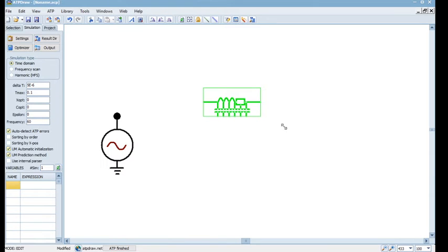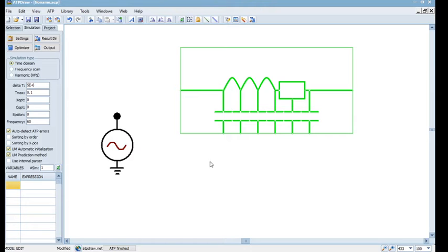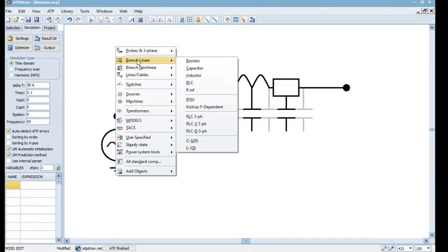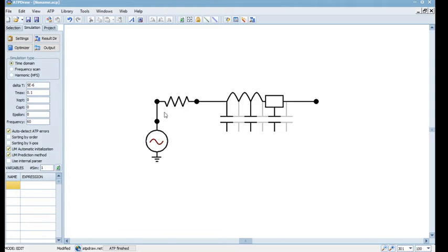Let me just make it a little big. I can do this always. Fine, and then a resistor element, so linear, and then go to resistor here. That's it. Yeah, one more thing which will bug you, like this comes with experience again, is in case you want to move this branch, so how to do that? You need to just left click, long press, so you can move these